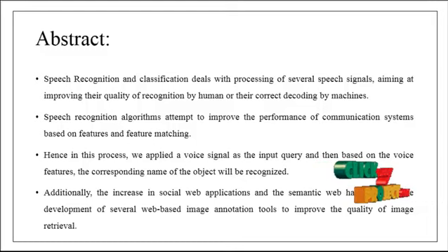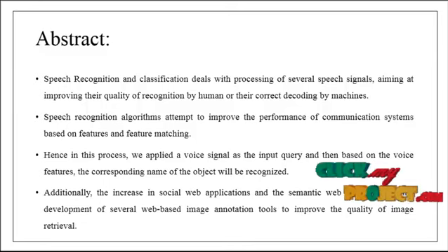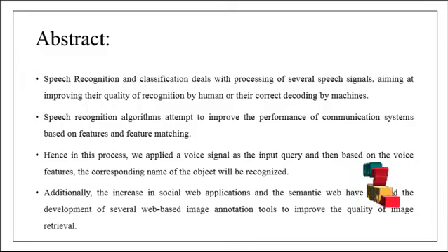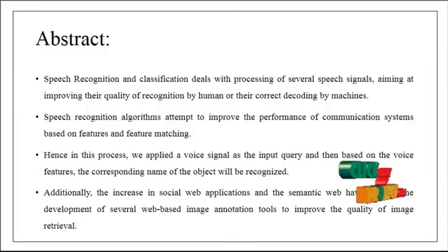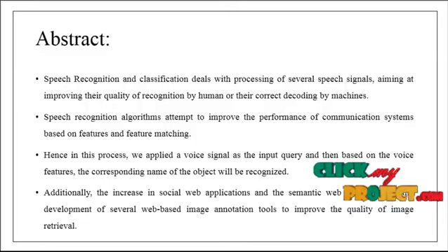Speech recognition and classification deal with the processing of several speech signals, aiming at improving their quality of recognition by humans or their correct decoding by machinery systems. Hence, the speech recognition algorithms attempt to improve the performance of communication systems based on feature matching technology. In this process, we apply the voice-based signal as an input query, and then based on the voice features, the corresponding name of the object will be recognized by using the feature matching process.